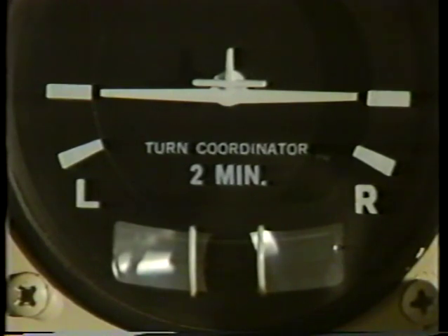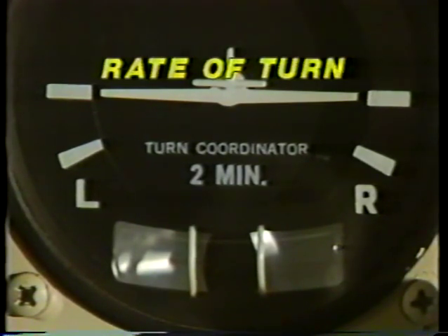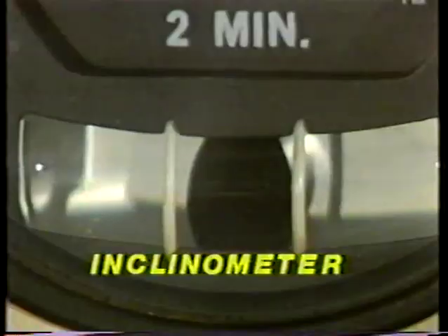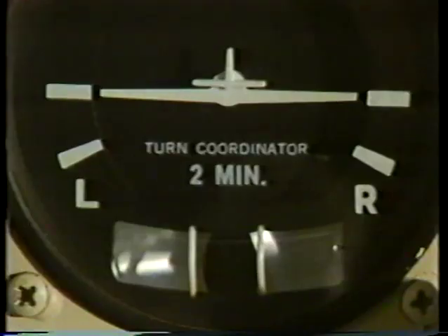The upper gyroscopic indicator displays the rate of turn and the direction of turn. The bottom portion, sometimes referred to as the ball, but more correctly as the inclinometer, displays the yaw information. The turn coordinator shows a miniature airplane, reference marks, and the words 2-minute turn.